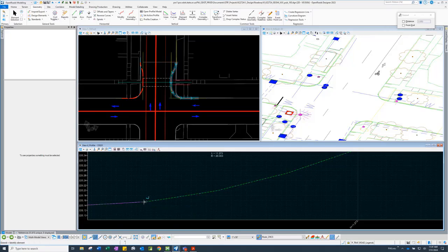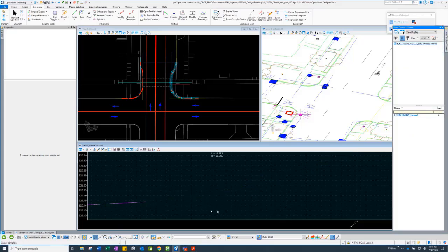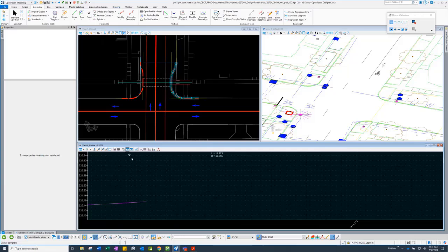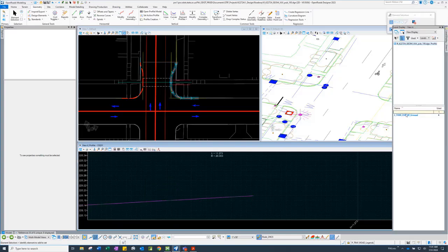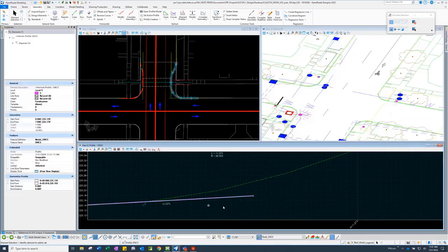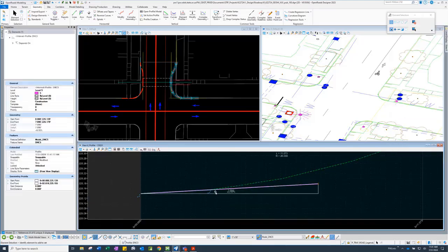You use the extend, hang on a minute. You have to turn the existing ground off sometimes because it doesn't like to let you snap into it. It thinks it's more important. So there. So now this is, again, ruled by 2 points. And yet you can see that snap is still there on the existing ground.